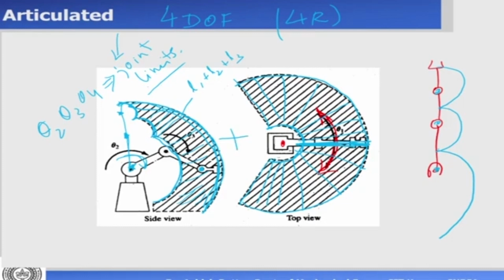It will be part of a sphere. It will be spherical, and inside there are going to be parts which are left out. So from the top view, when I combine this one and this one, it will be part of a sphere. It is going to become a spherical shape. This is how we get the shape of the work volume of different kinds of robots.